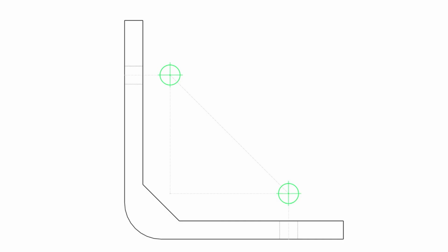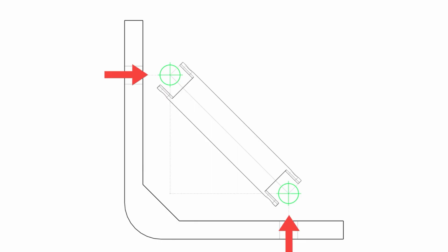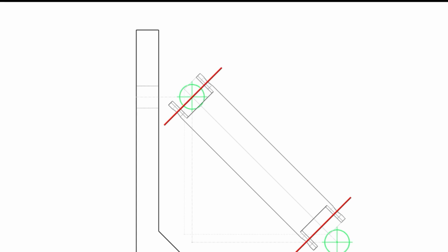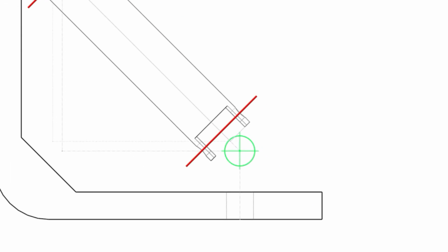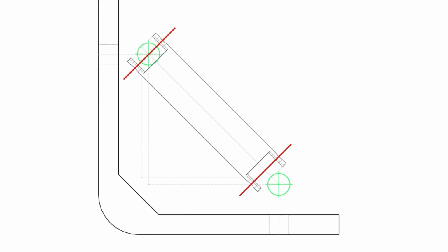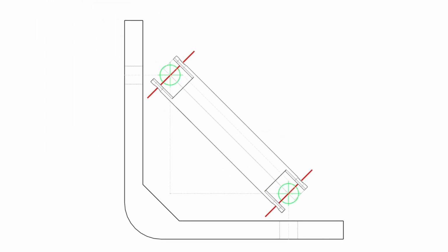Okay, we extracted the dimensions for the shaft from this sketch block, but these points were the location of the rotation axis and I mistook them for the overall length of the shaft. So by adding the first concentric mate, it wasn't possible anymore to align the other side of it. I corrected the length and the problem is solved.